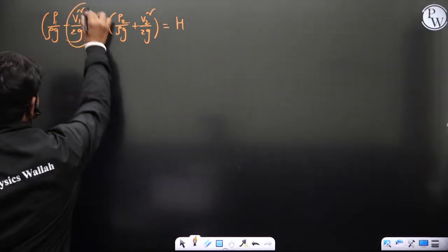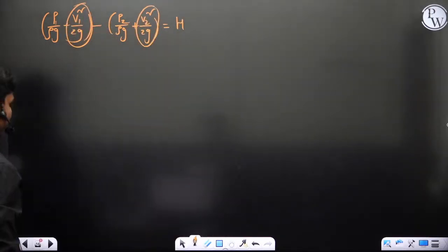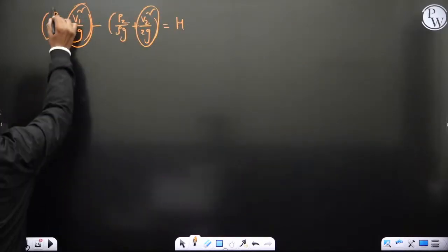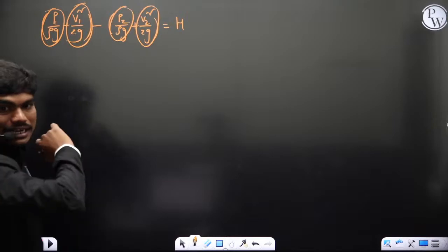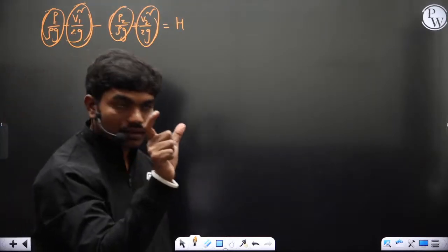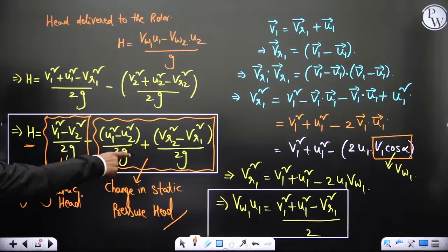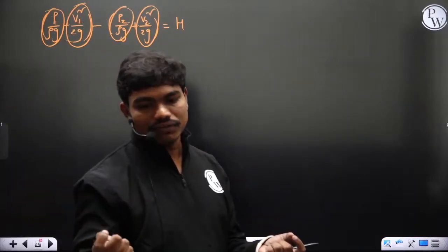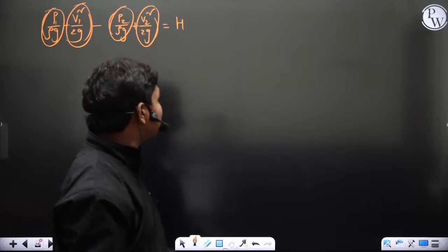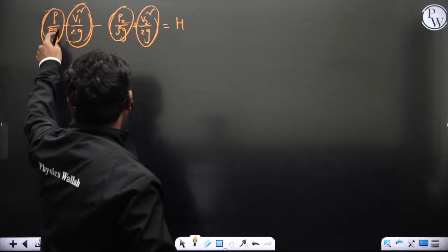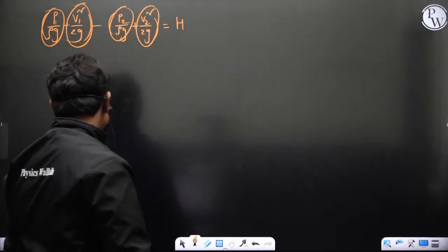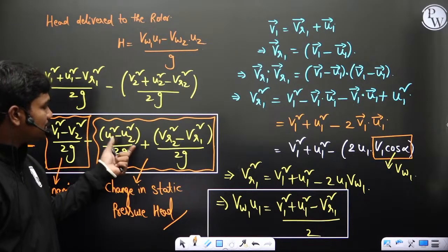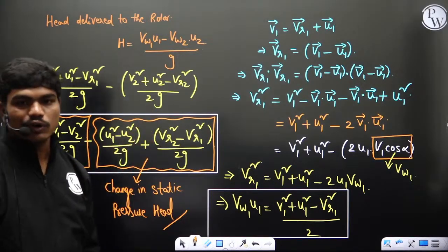Now clearly you can see this term, V1 squared minus V2 squared by 2g here. This part is due to P1 minus P2 by ρg. That part of the complete energy supplied belongs to the static head. Now sometimes, suppose the inlet and outlet of the fluid are both open to atmosphere, so P1 and P2 are the same, then clearly this term will be 0, and this complete summation will go to 0.